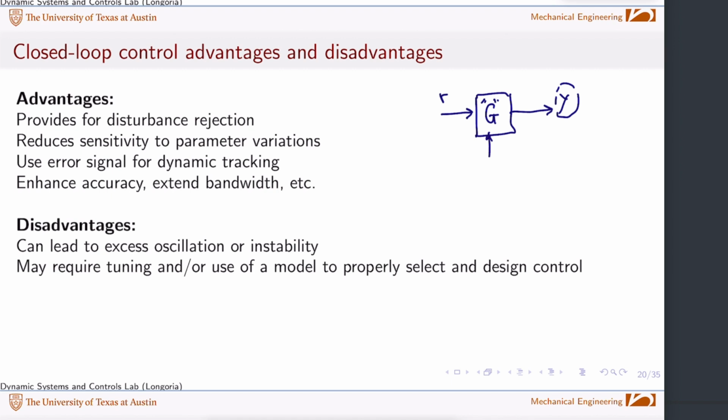You can also implement tracking of the reference input. On the input side of that controller, here's your error, here's the feedback coming from your measurement, and here's the reference. Sometimes we talk about if the reference is just constant, or you're trying to regulate something, we call it a regulator. Say you're trying to keep it at zero, but R might also be changing.